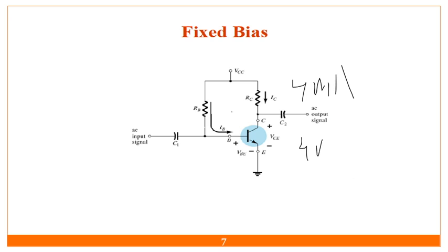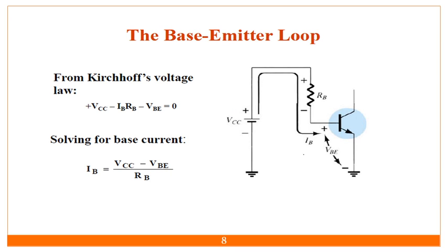So if I am thinking about the input, apply a KVL. This is a structure that we have to draw. So apply KVL to the input. Minus to plus, I have to write plus VCC. Then plus to minus, I will write the drop that I have to calculate. So this is nothing but my VB drop over here, and the VB is denoted by RB into IB over there.